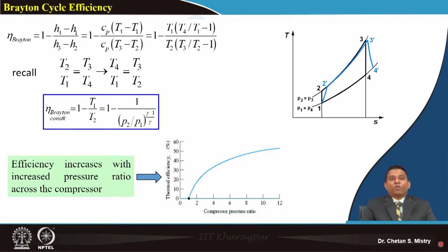For a gas turbine power plant, if you want to increase thermal efficiency, it says you increase your pressure ratio. So increase of pressure ratio is demanding for so many things. You can go with a pressure ratio of 10. As of today, people are talking about having an overall compression ratio of 64. So this requires some kind of detailed understanding.